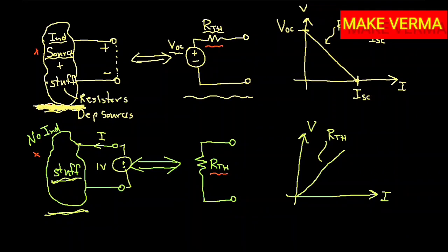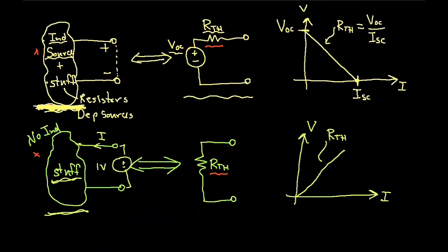So again, this is an introduction to the Thevenin equivalent circuit, or the Thevenin theorem. And again, this is extremely useful. It's not particularly useful to just solve circuits, as a lot of the textbooks will give you the impression, but it is extremely useful to allow you to take lots and lots of stuff, boil it down to an equivalent source and resistance, or just an equivalent resistance, and then use that to do some analysis. So anyway, that concludes this video, and subsequent videos will give lots of examples of how to actually compute these things.